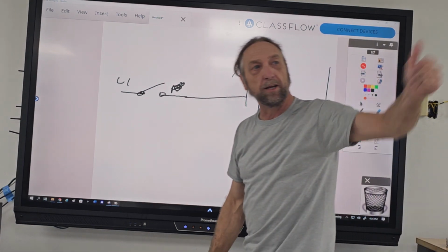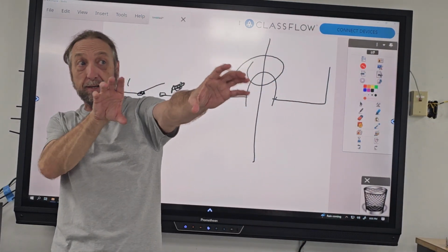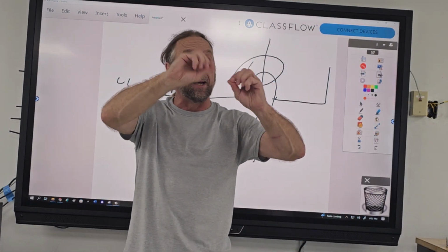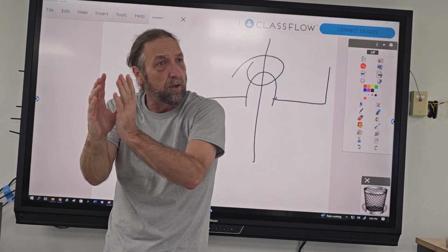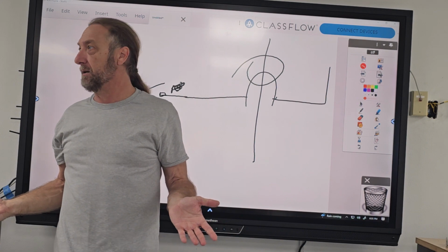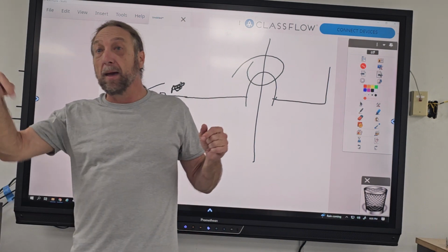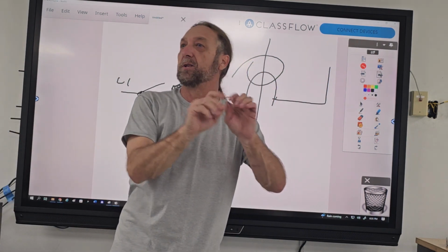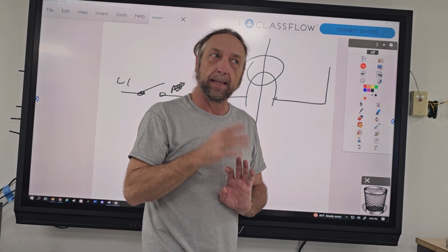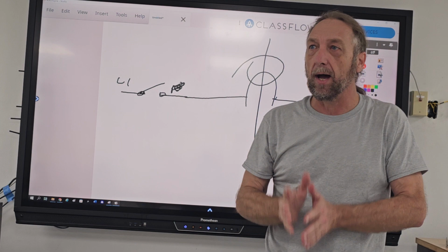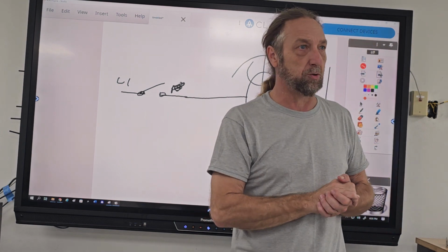So in the wall, let's just say you wanted to put an outlet right next to those switches. You have a light switch in the bathroom, and you want to put an outlet right next to it. You have no neutral there to put an outlet. Now, they may have a neutral inside the box, but it's not connected to the switch. Neutral and line one do not connect to the same switch.